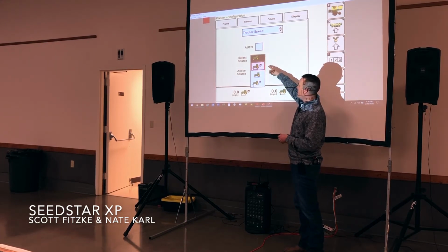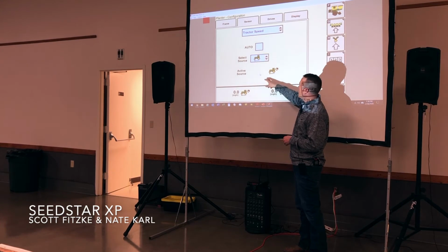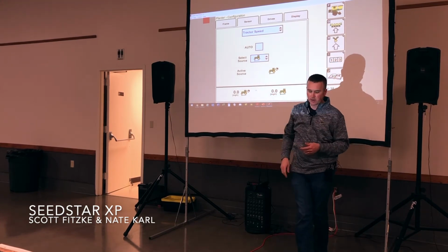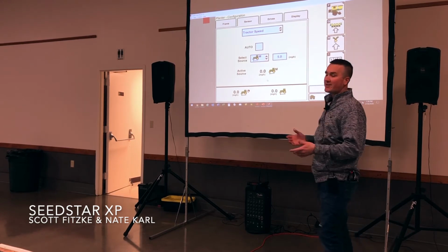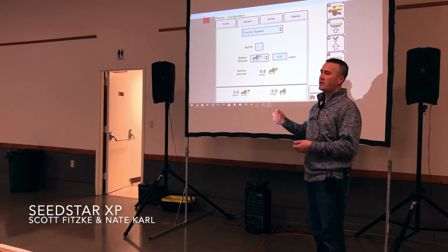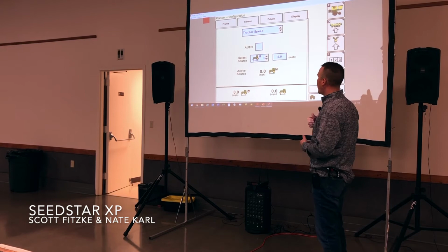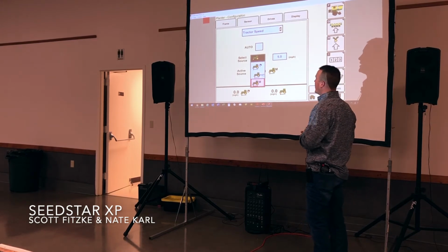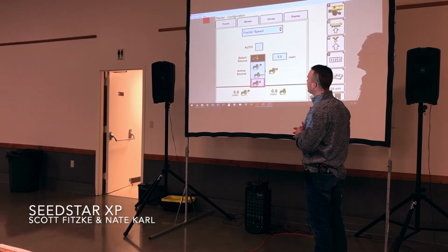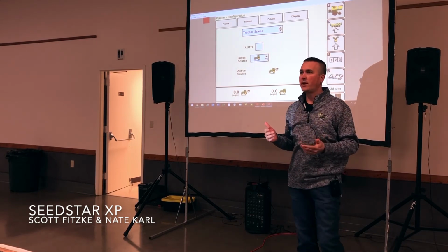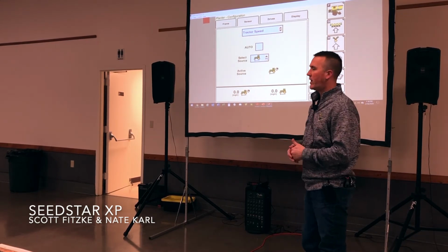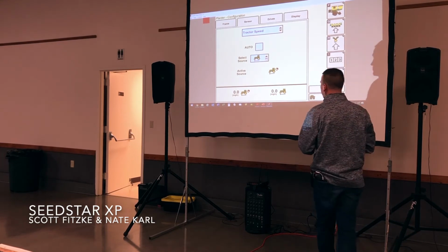So that'll be picking up any type of radar speed if you have a radar in your tractor. This will be a wheel or a transmission speed. And then the manual speed will be if you're entering just a straight speed. So if all the satellites fell out of the sky, we could in theory still run by putting in a manual speed without any other information to take off. I really wouldn't recommend that, as our population basically is set because it expects that we're always traveling that speed no matter what.